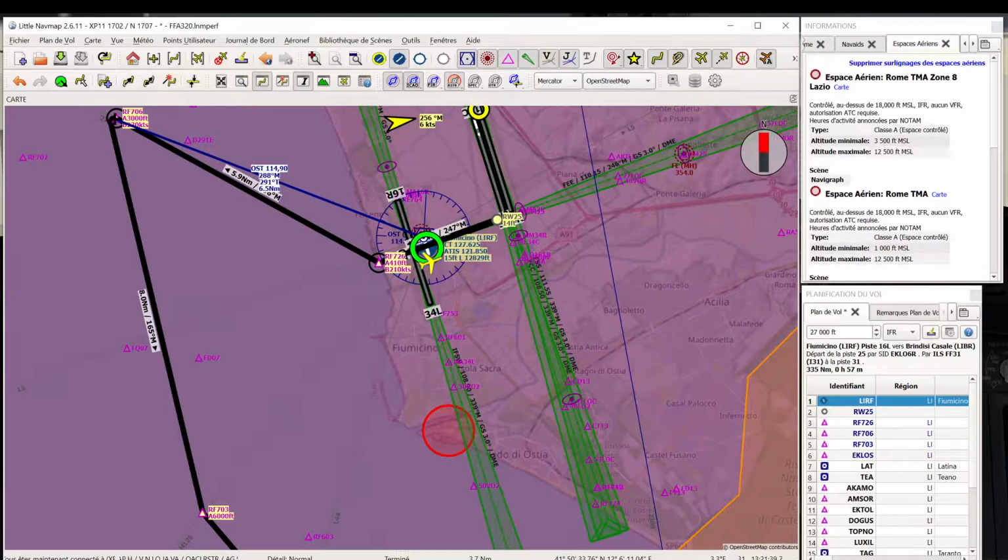So then we turn left, and because it is a sharp turn, you also see that we have to be above 3000 feet, but below 230 knots. And we go left on heading 165 till the waypoint Romeo Foxtrot 703.